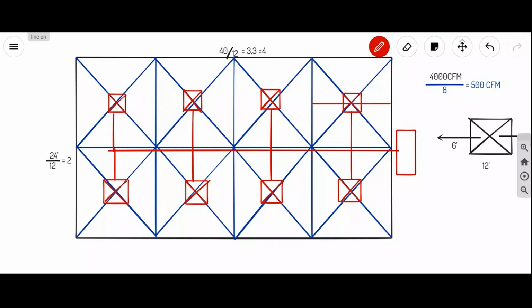Now what happens in real time? We may not be seeing the real time. In real time there may be slight changes. Somewhere I'll take a short radius elbow, but there is a beam or column coming. So instead of a short radius elbow, the site engineer will take an instant decision and make a long radius elbow. So there may be little changes on the site.